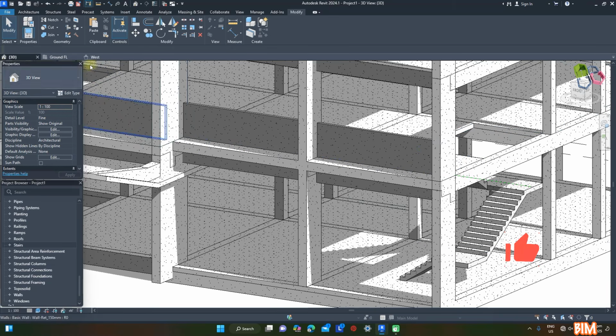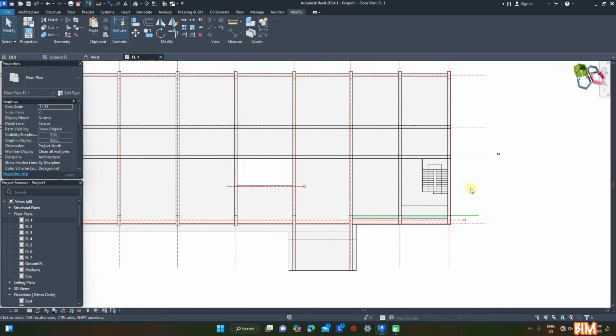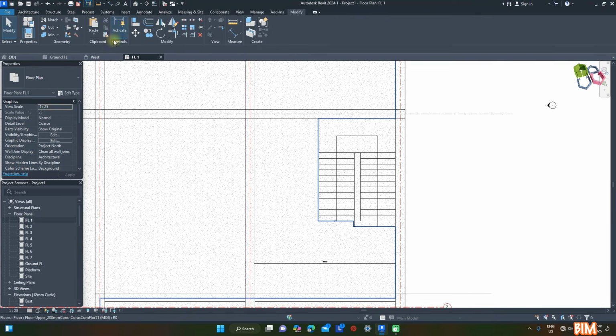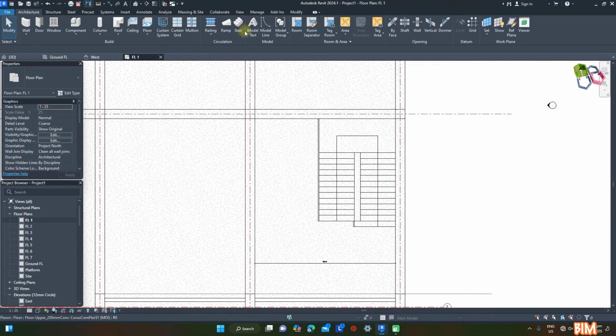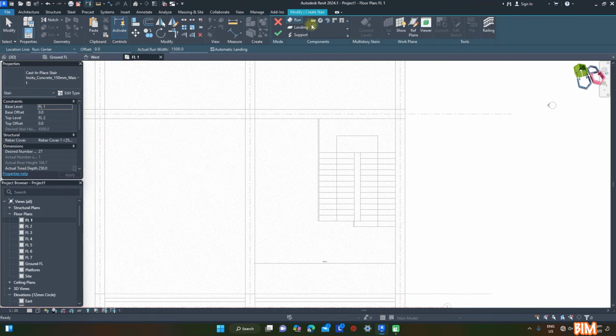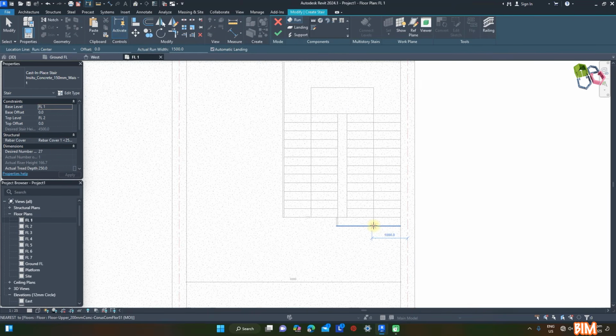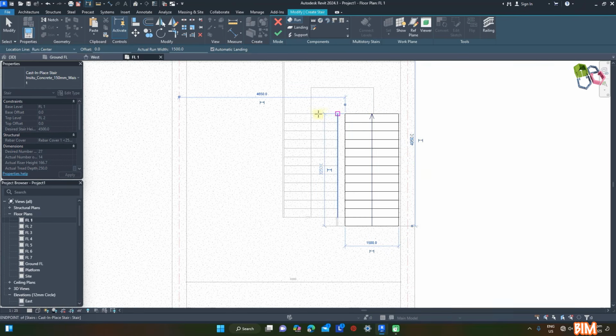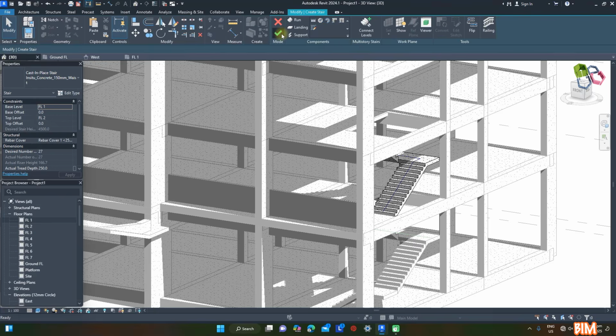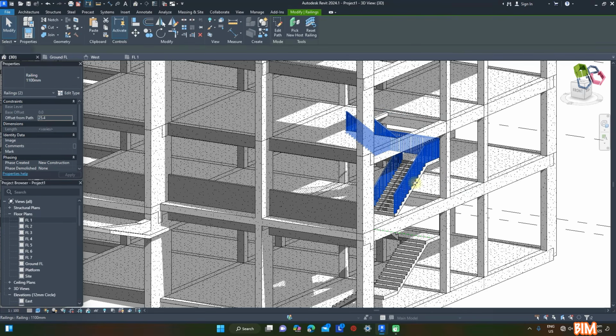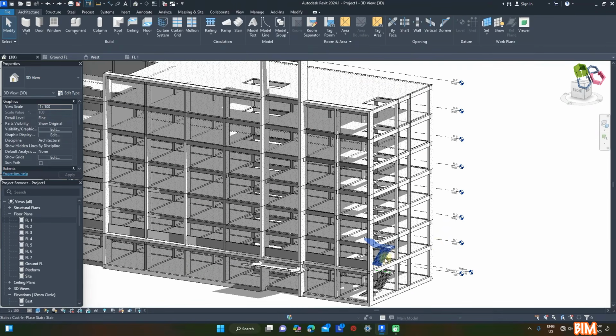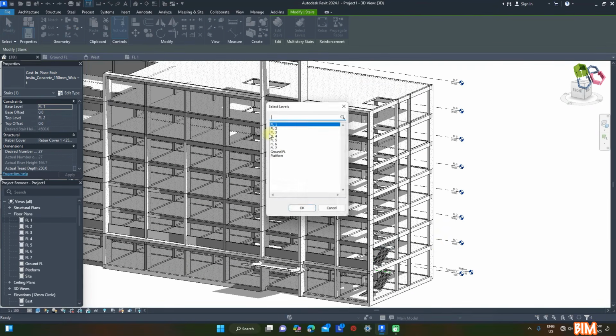Next, install the stair on floor level FL1 connecting to FL2. Same process as previous, but in this case 2 flights run, due to the reduced floor height. For this stair, FL1 to FL2, Revit calculated 27 risers in total. So run the below flight for 14 risers first, and then 13 risers. Remove all railings for this project. Copy and install on each level above up to FL6.